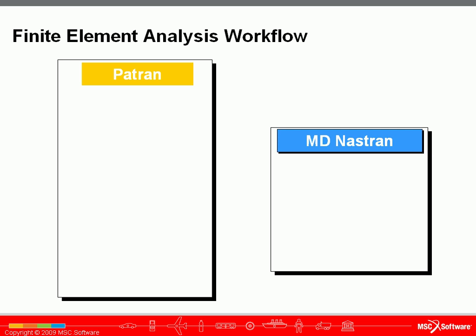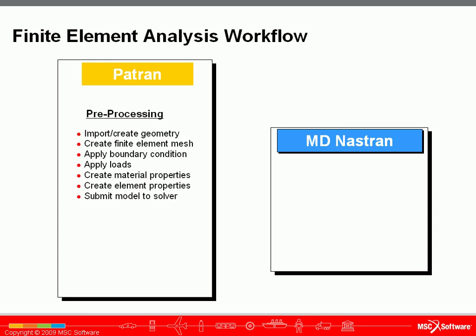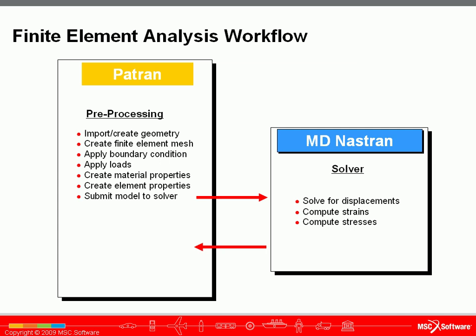This slide illustrates the finite element analysis workflow between Patran and MD Nastran. Patran does the pre-processing or model creation where you import or create your geometry, create your finite element mesh, apply loads and boundary conditions, create material and element properties, and then submit your model to the solver, in this case MD Nastran, which solves for displacements and computes strains and stresses, before writing out a results file which is read back in to Patran. Then post-processing can occur where you create deformation plots, fringe plots, or reports.